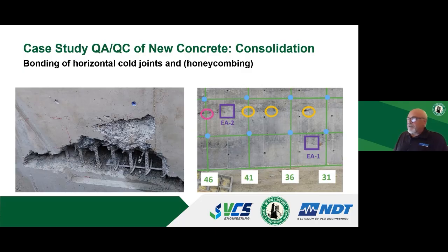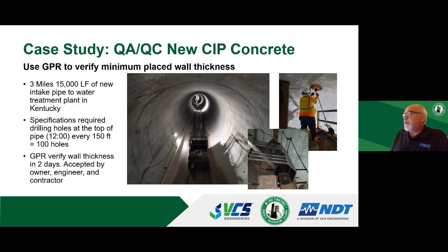Maybe it's July, we're waiting for a concrete truck for an hour or two, or stuck in traffic, and is that concrete bonded, upper concrete bonded to the lower concrete? Well, if it is bonded, then the energy waves will cross over. If it's not, they won't.